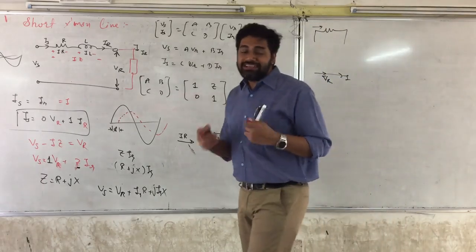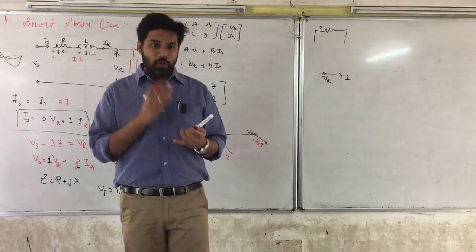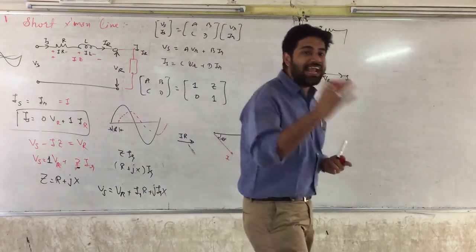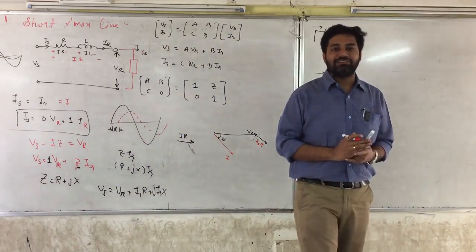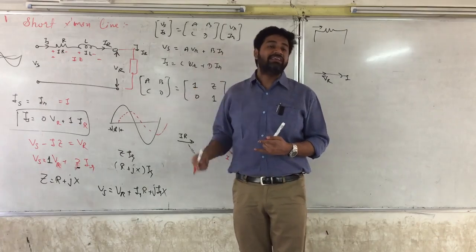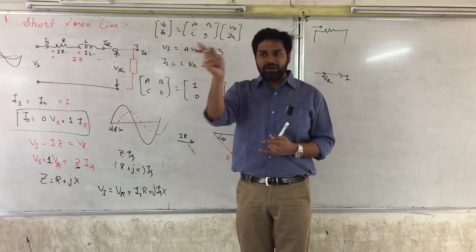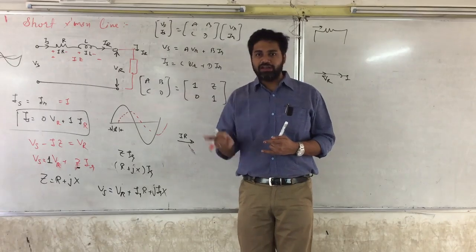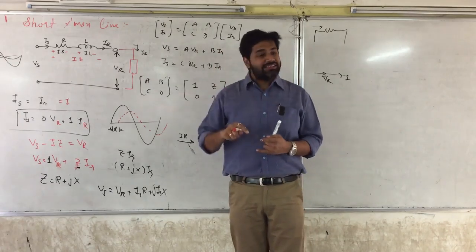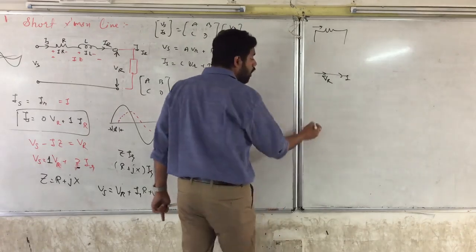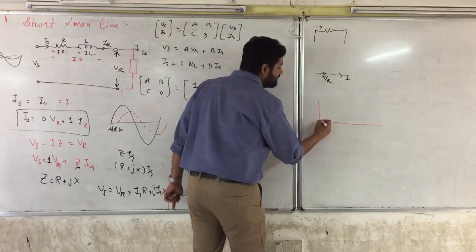When I say active power is a net power loss, and reactive power is not a net power loss, net power loss is equal to 0, you should have the entire theory behind it in your mind. How exactly voltage and currents are there in a pure inductive circuit, you should know. How exactly multiplication of voltage and current gives you a curve of frequency 2 omega t.